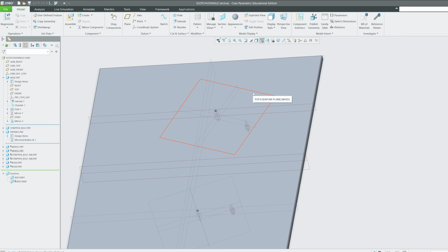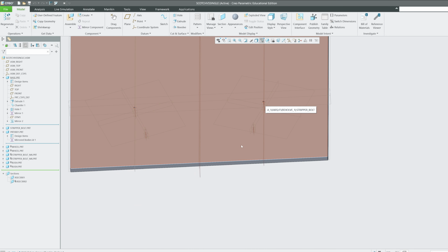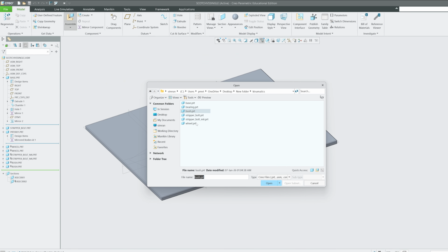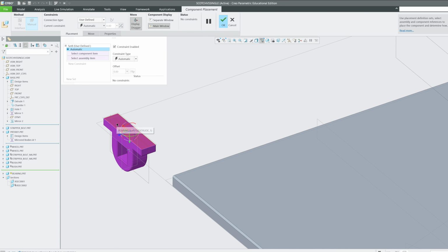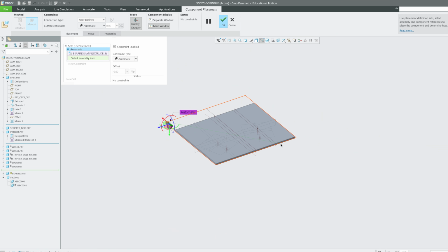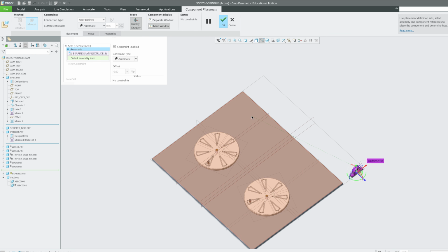Whenever I make any change, it will automatically get shifted, or even if I am reducing it somewhere, both bearings will always be aligned. Now let's go to assemble, click on bearing. I'm gonna choose base to base because this one needs to have 0 degrees of freedom, so I'm not going to make it move freely.